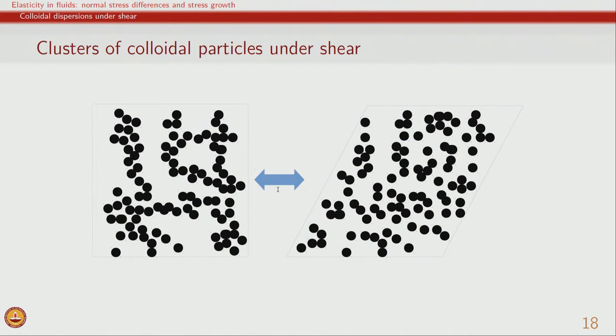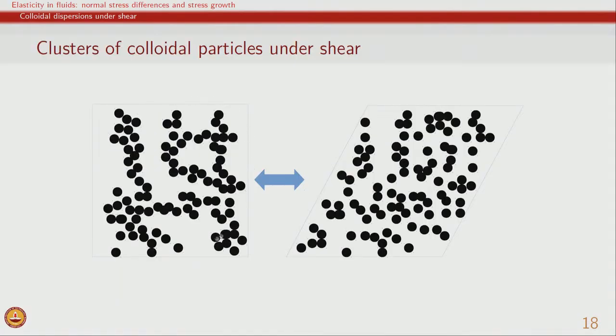And to do that let us again consider the colloidal particles under shear, and this qualitative picture we have seen earlier also. If a colloidal particle system is stationary, it will form clusters of particles, and they are all networked with each other, and basically we have a percolated structure, and therefore in general the viscosity of such systems we said will be higher.